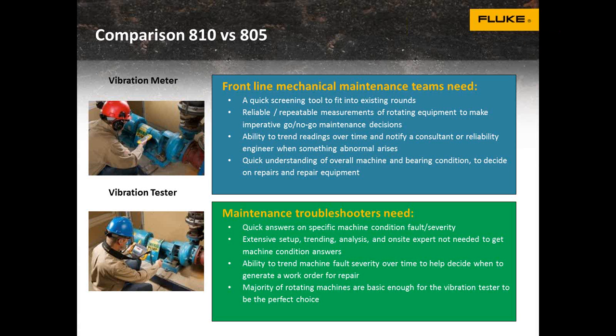By following that pattern, we can identify roller bearings without having to know the bearings or the bearing database. The problem we found in the earlier days of bearing analysis is that if you had the bearing tables, you could find the exact bearing frequencies, but not everybody knows what bearings are inside their machine. If you don't know the bearings, then a bearing database or bearing tables aren't going to do you any good. So instead, we follow the patterns that all roller bearings follow, and that way we can tell you what bearings are going bad in your machine without knowing what bearings are in there.